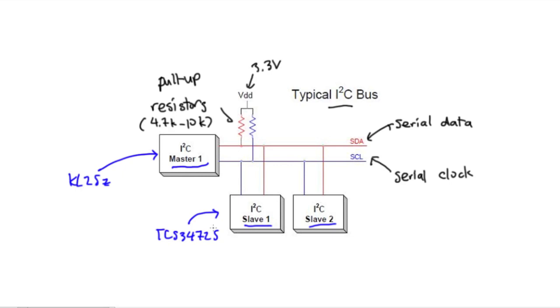Well, you also have to consider the idea of scalability when it comes to digital communication protocols. The advantage of this I2C bus is that if you want to access multiple different devices, you can attach more I2C slaves to this particular protocol just by making sure that one wire is connected to the data line and the other one is connected to the clock line. This in turn means you can have a near infinite amount of different slaves. This makes it very, very versatile because you only need 2 digital pins to access 100 different types of slaves if you want to.